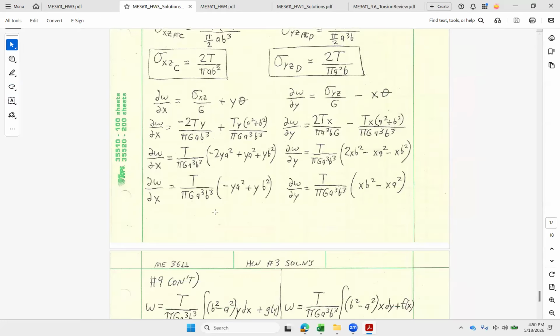Last thing is the warping, all right? I know that my warping formula for the circle came out flat. For the triangle, we saw it had kind of a three-way, three-legged saddle undulation, positive, negative, around 6 spots. And then here are dw/dx, warping with x, and warping with y.